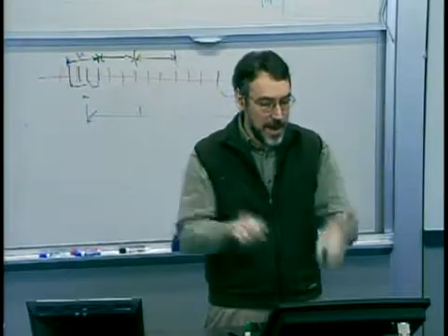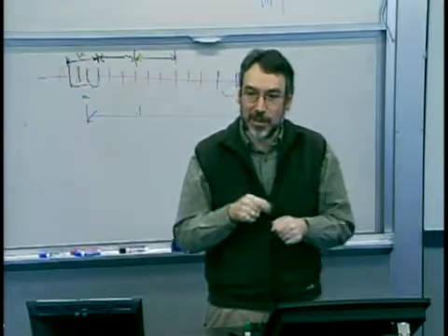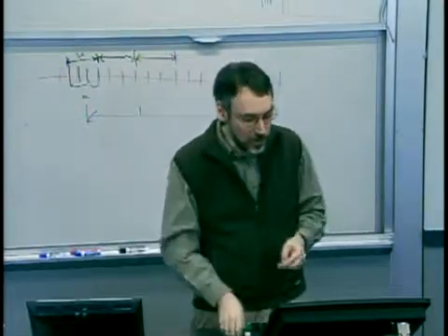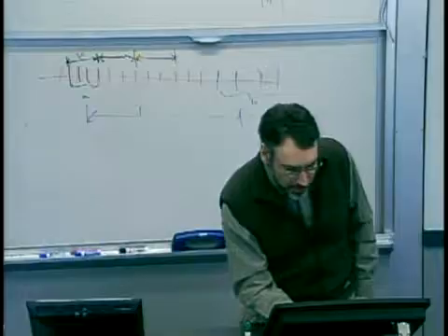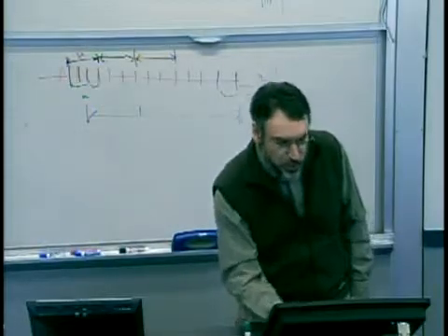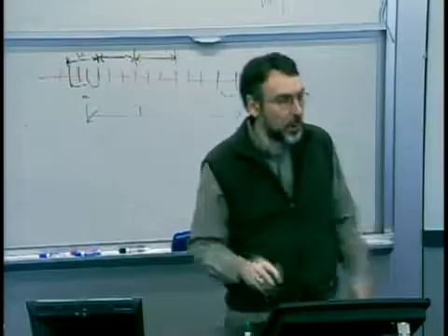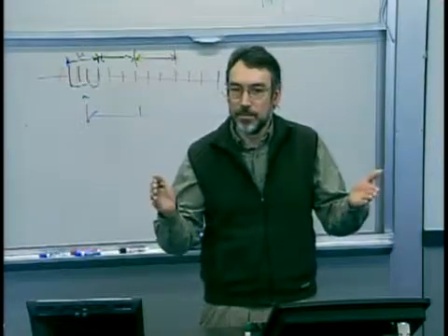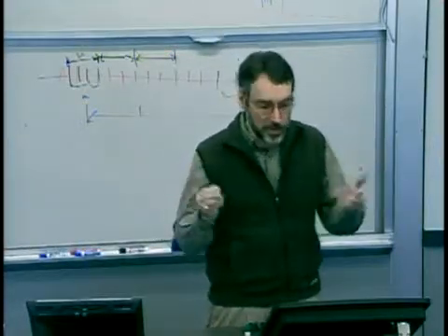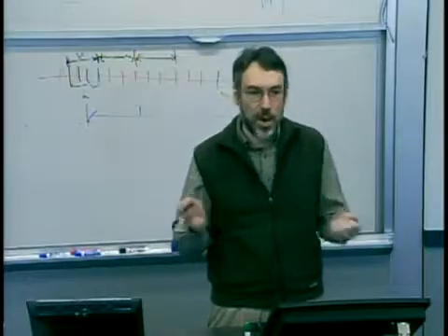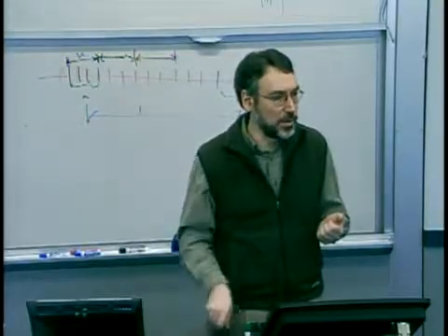Okay? And as pictured here, I am perfectly centered, so my CPK is also 1. In other words, my minimum distance between mu and my upper spec limit, or mu and my lower spec limit, is both 3 sigma. So the minimum of those two is still 1. So my CPK is 1.